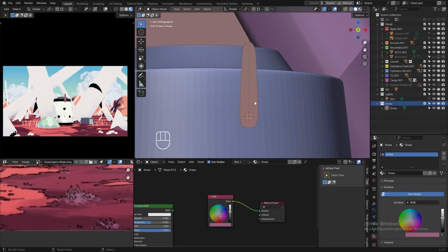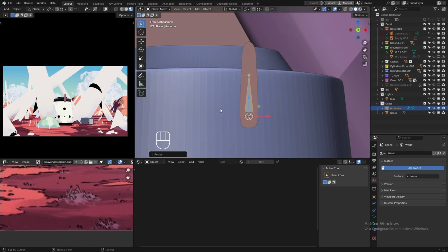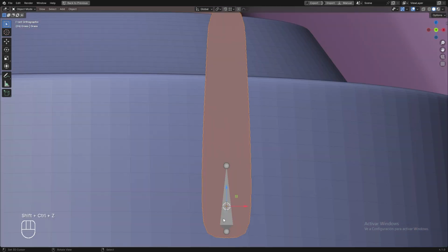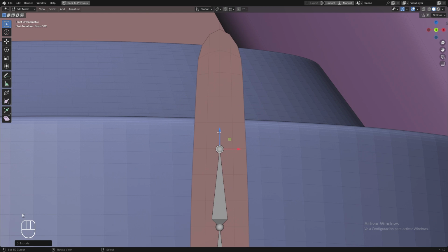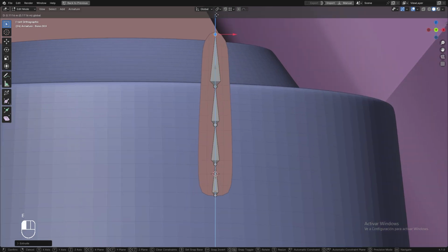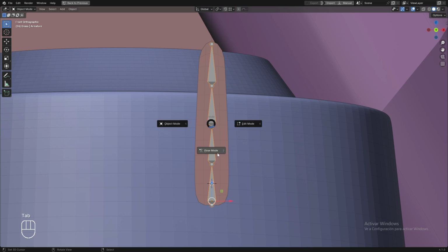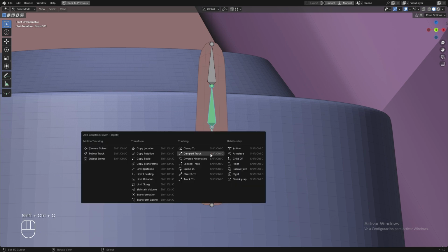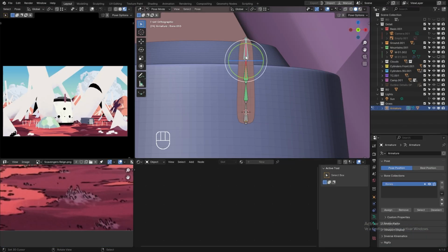For the grass animation, I used the wiggle bone technique. It consists of adding an armature and in edit mode, extruding the necessary bones. Then switch to pose mode and select the last bone and the nearby bone. Then press Ctrl plus Shift plus C. Choose damped track and repeat the step for all the other bones, just leaving the first bone.